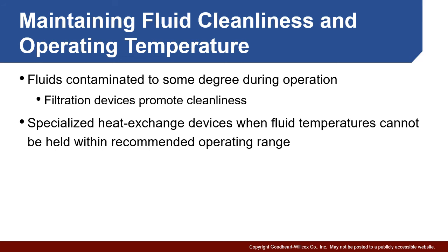If we're in a situation where temperatures are unable to be regulated solely through the reservoir, we can also add specialized heat exchanging devices that may heat the fluid up. For example, we talked about that in cold weather environments, or we may have coolers if we have a system that's going to be generating a lot of heat. So we're going to have a wide variety of equipment out there. We're going to discuss more in future units that are specifically designed to maintaining those important properties of our hydraulic fluid.